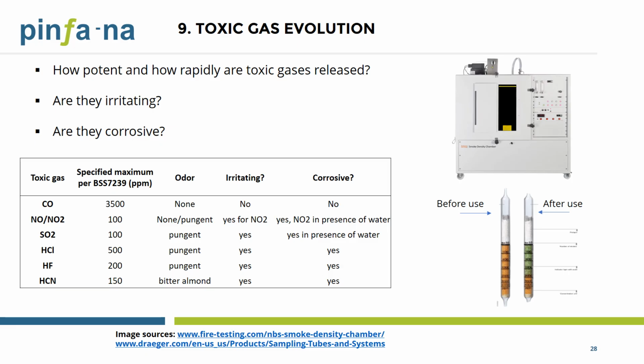Here we look at the Draeger tube method in a little more detail. The Draeger tube is also called a colorimetric chemical sensor. A Draeger tube is a glass tube filled with a chemical reagent and a filter layer that can react with a specific gas substance and turn color as a result of a chemical reaction. The substance conversion in the tube is proportional to the mass of the reacting gas. It is possible to indicate the substance conversion as a length of discoloration on the tube. So if a fixed volume of sample air or smoke flows through the tube, the concentration of the test substance can be directly read out as a length of discoloration on the tube.